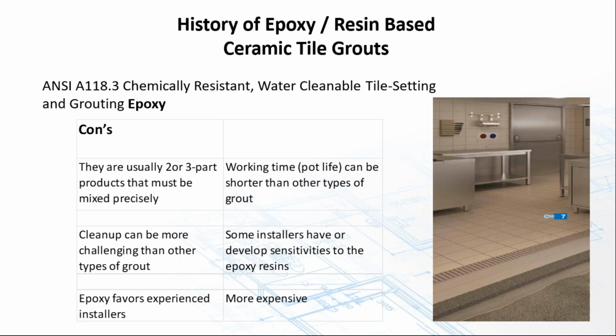Being aware of those conditions with epoxy. The other thing with epoxies, remember one thing: in direct sunlight, the lighter colors can be UV sensitive, just like if you're working with epoxies on a surfboard or any other type of plastic application under UV light, lighter colors can tend to yellow over a period of time. Similarly, your lighter colors of epoxy may tend to yellow. Check with the manufacturer if that becomes a concern, making sure what they tell you regarding their epoxy grout.